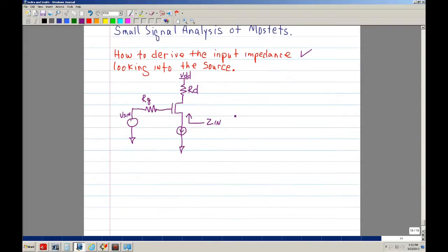Anyway, let's say for example, if you take the output at the drain, say this is out, and this is your input signal, that would be your gate, and that would be your source. Okay, so if your signal comes in on the gate and it comes out on your drain, then this topology would be a common source.